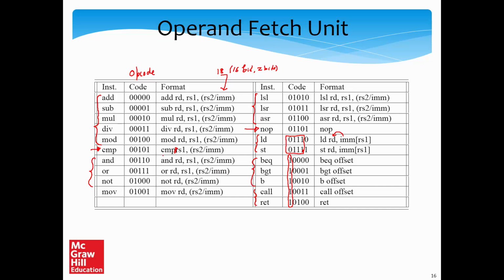So essentially, in opcode design, we have to look at how easy it is to understand and how quickly we can decode an instruction. So it is always a good idea to group similar instructions and give them similar opcodes. For example, all the branch instructions we have given an MSB, most significant bit, of 1, which has made our instruction design very easy. It's very easy to find out if an instruction is a branch or not. We just take a look at its MSB. And for load and store also, we have to take a look at its first 4 bits, but that's also easy. That's not very hard to do.